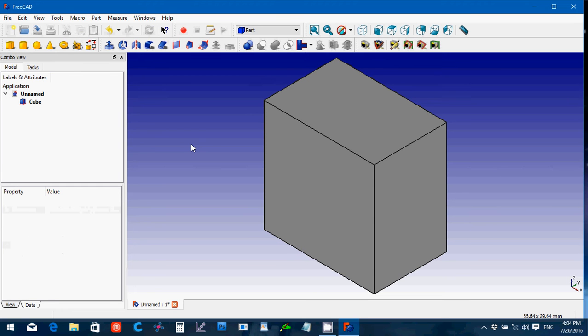Now, you're probably going to wonder why I am not just creating two cubes and then attaching them together for the bar parts. The reason is that we're going to be trying to create a fillet in both parts of the corner. If you had two different parts, the fillet would be limited to the height of the bar piece itself, which would not work out very well. And the bar piece is, let's see, 1.5 millimeters.